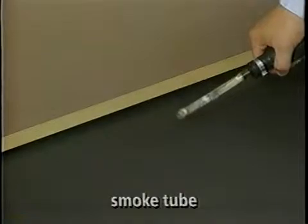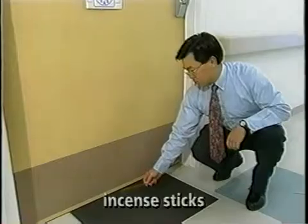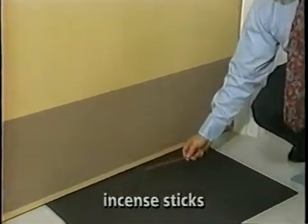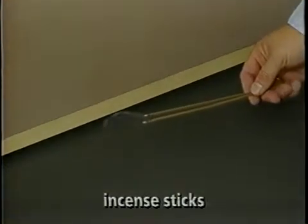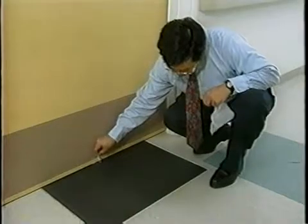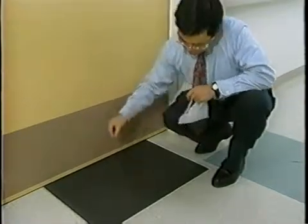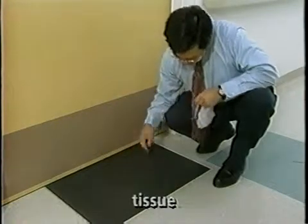The test should be repeated at least once or until the results are consistent. If smoke tubes are unavailable, you can use incense sticks to generate a stream of smoke. In this case, we recommend that you use at least 2 sticks. Lastly, you can also confirm negative pressure using a telltale device, which can be something as simple and readily available as a piece of facial tissue.